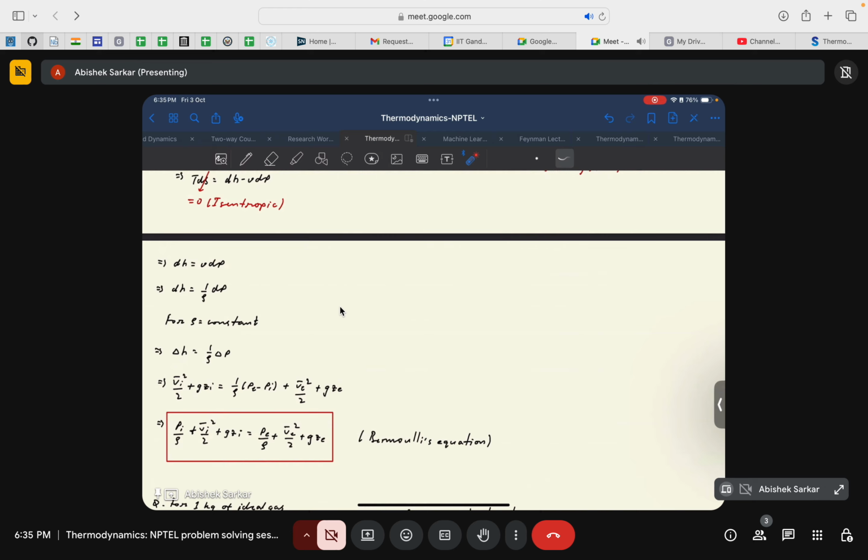Viscosity would generate boundary layers, would generate velocity gradients, which may cause viscous dissipation, which can be taken as the internal irreversibilities that can occur when we consider viscosity of the flow. Since this equation is valid for inviscid flows, like one of the assumptions that we use to derive this Bernoulli's equation, that's why this equation is valid when no internal irreversibilities are considered. Okay.